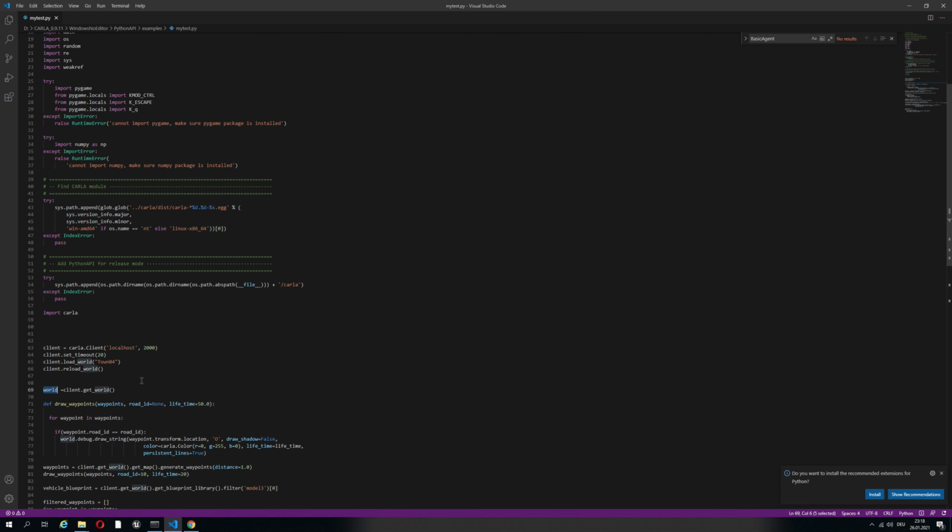Now, this is one way. There's also another vision technique, which is semantic segmentation, where you don't look only for the lanes, the text lanes basically, but you segment the scene into different labels. One of them would be streets, and one would be lane, and then you can use that again to estimate your path.